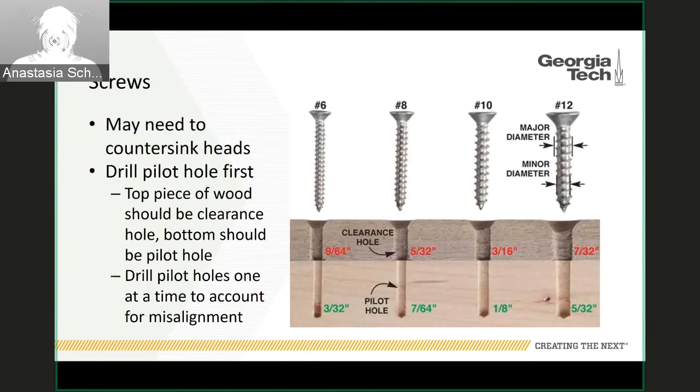The pilot hole is going to be undersized instead of a clearance hole, and that allows you, when you are screwing the screw in with the drill, enough room that the screw can go in fairly easily. It's not going to break or anything, but there's still plenty of material left for the threads to bite into.